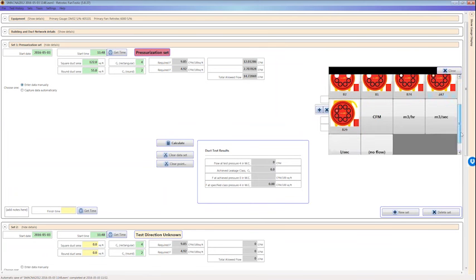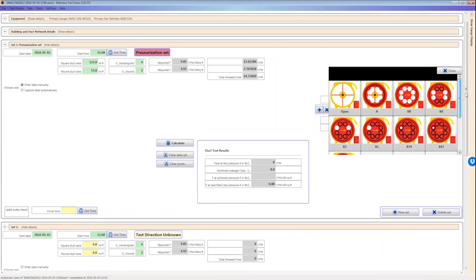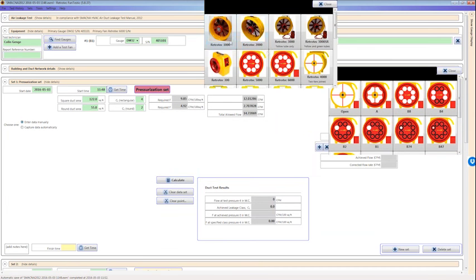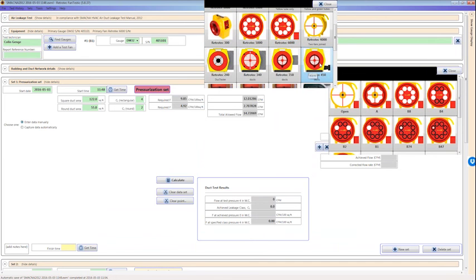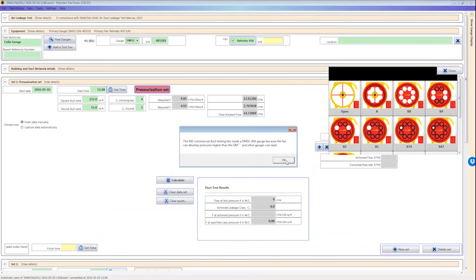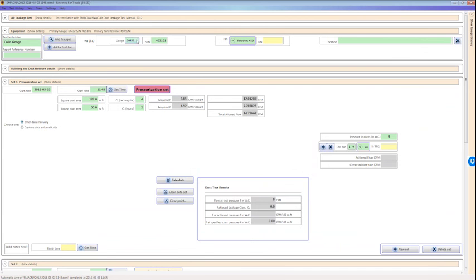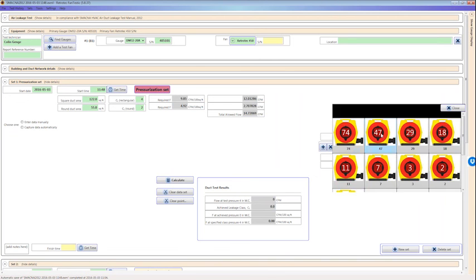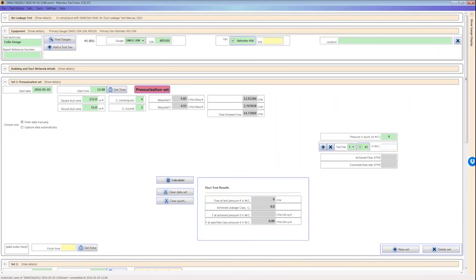In the model 441 versus 451, the 4 stands for testing only in the pressurization direction. The 5 in 451 means you can test in either direction, and you get that little attachment that goes over the front of the fan. So just wanted to clarify that. If you have a 441, you can still buy the attachment and use it as a 451. So just because you may have bought a 441 doesn't limit you. It's a relatively inexpensive add-on.